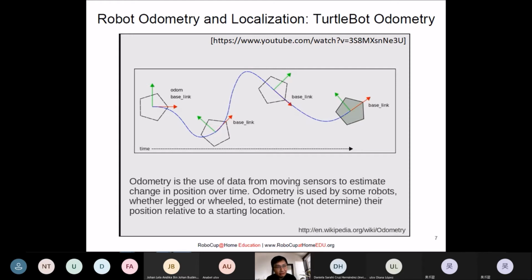So you use the odometry way to calculate the change in movement of your robot over time by using the wheel information. For example, how much it turned over time, or if you know the speed, because if you integrate the speed, you get the distance. Those are the maths that I think you can imagine, but of course you can read more.